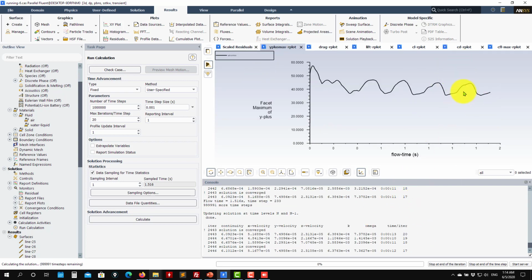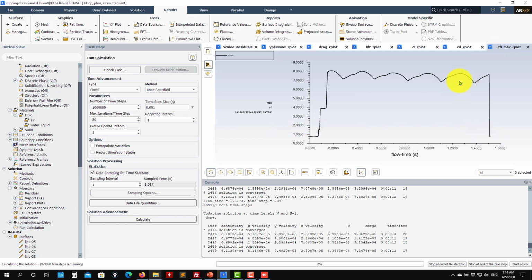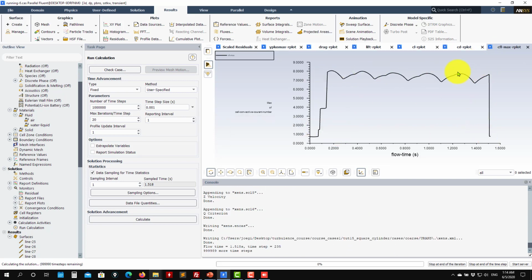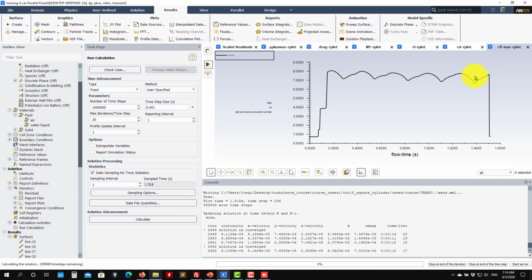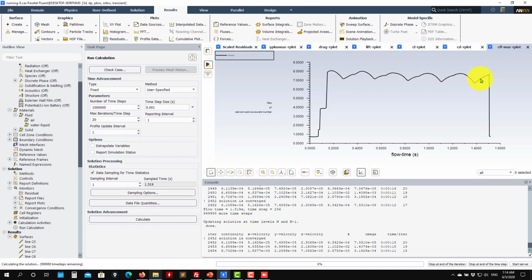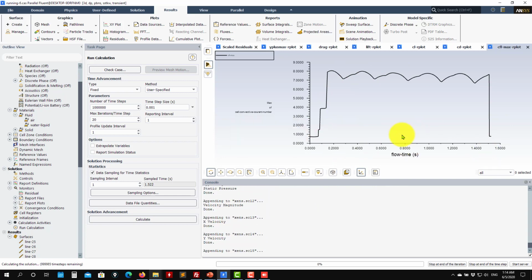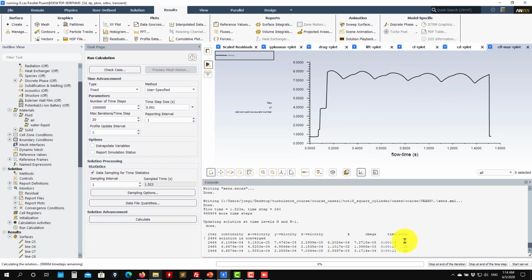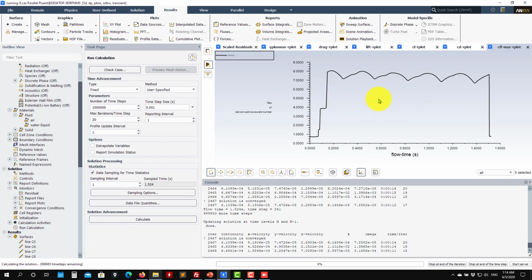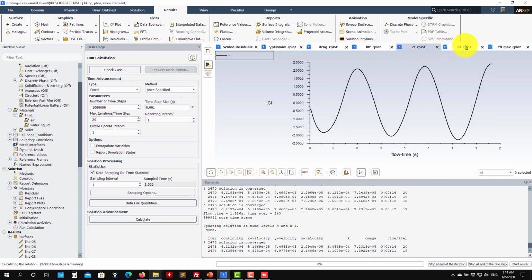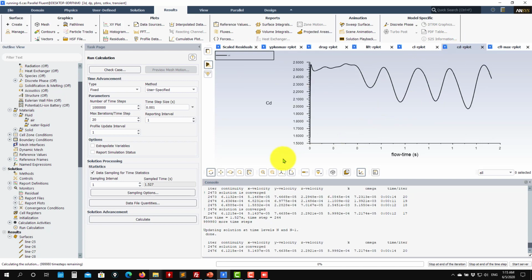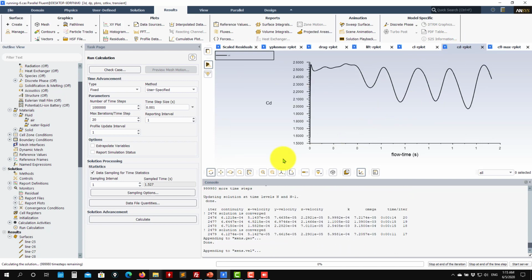And you get the point that I was telling about the CFL. To reach this time here, you just measure the clock time from here to here using CFL 10, and probably here it took 10 or 20 minutes to do the same period, but this time it probably will take 1 hour or more. So you see that it's still affordable and it's still within the 20 iterations limit. It was using the CFL of 0.01 because it was also resolving your frequencies well. These are things that you need to take into consideration at this level when you are doing URANS.